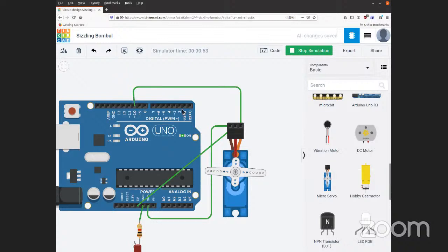And before I let you go and play around with some Tinkercad circuits, I'm going to tell you something relatively important. The Arduino Uno microprocessor is not fast. In fact, it is slow compared to most computers. And if you have too many operations in your program, your robot could drive over a line, even though it's constantly checking for lines, because it's so busy doing all those calculations. Now, realistically, it's not that likely to happen, but it could happen.